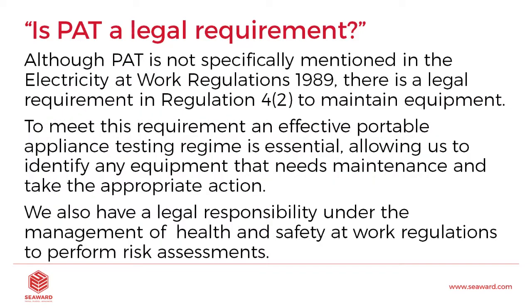So, although PAT is not specifically mentioned in the Electricity at Work Regulations 1989, there is a legal requirement in Regulation 4 Paragraph 2 to maintain equipment. To meet these requirements, an effective portable appliance testing regime is essential, allowing us to identify any equipment that needs maintenance and take the appropriate action. We also have legal responsibility under the Management of Health and Safety at Work Regulations to perform risk assessments.